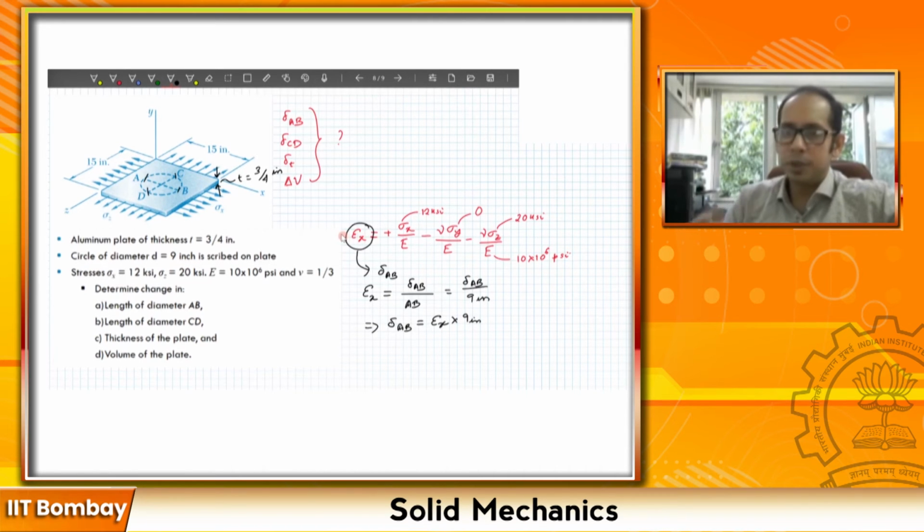You have to be careful in substituting the numbers, in the first equation which we wrote for the strain in terms of the stresses, the ksi, the psi, and so on. Remember, 1 ksi is 1000 psi. So with that, you can easily calculate this one.